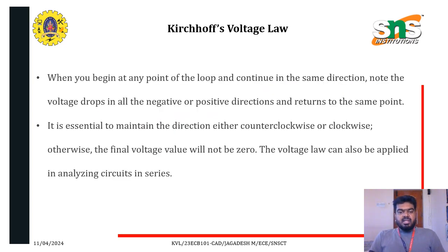When you begin at any point of the loop and continue in the same direction, note the voltage drop in all the negative or positive directions and return to the same point. It is essential to maintain the direction, either counterclockwise or clockwise. Otherwise, the final voltage value will not be zero. The voltage law can be applied in analyzing circuits in series.